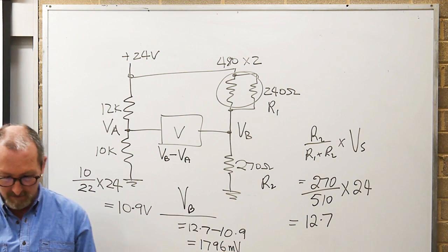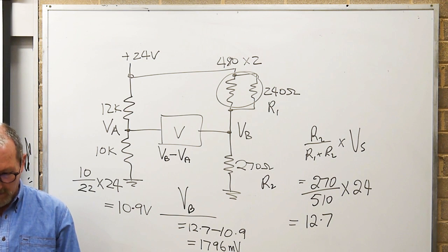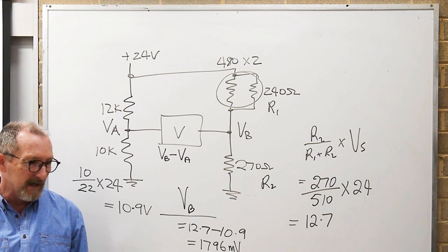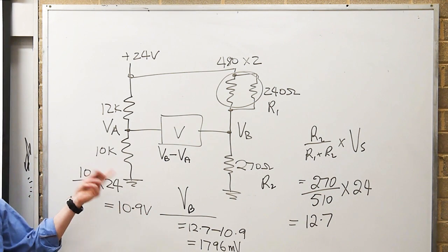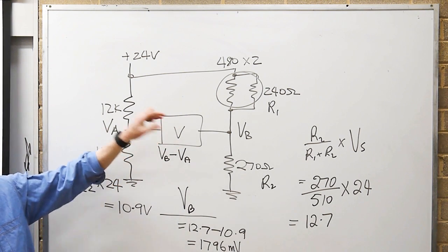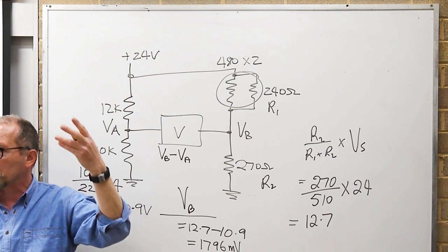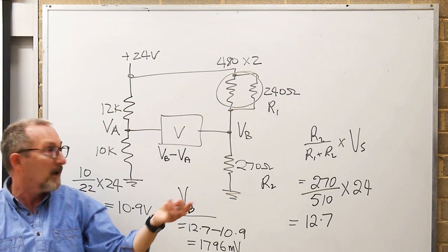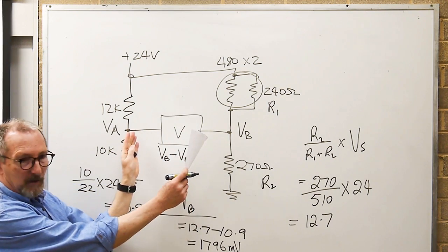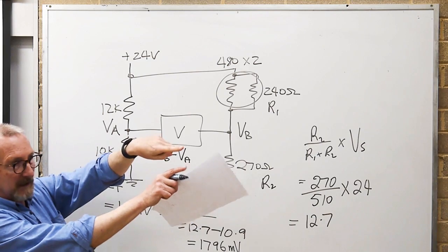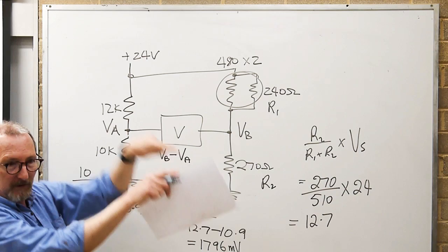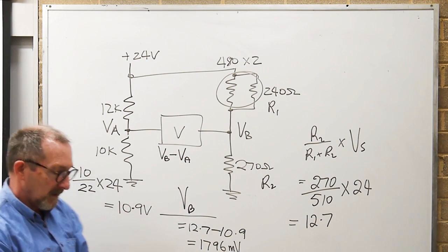1.79 volts. Again, make sure you learn how to do this. It's basically derived from the Wheatstone bridge work that we did, and looking at 2 voltages, and again, it's not too much different to the comparator question we had in question number one. Comparing the voltage there with the voltage there. In this case, though, we're just comparing it with a voltmeter instead of using that little triangular comparator device, which was looking for any difference between them. Any questions about that?